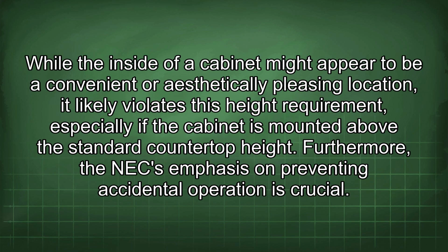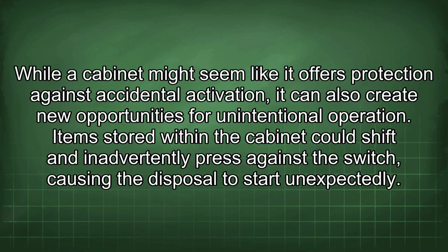While the inside of a cabinet might appear to be a convenient or aesthetically pleasing location, it likely violates this height requirement, especially if the cabinet is mounted above the standard countertop height. Furthermore, the NEC emphasis on preventing accidental operation is crucial. While a cabinet might seem like it offers protection against accidental activation, it can also create new opportunities for unintentional operation. Items stored within the cabinet could shift and inadvertently press against the switch, causing the disposal to start unexpectedly.